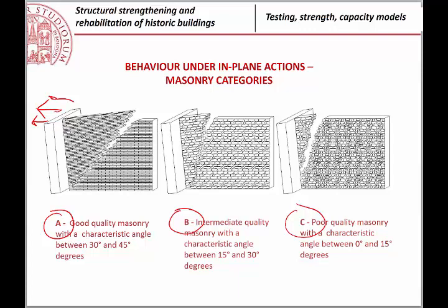talking about what Professor Borardi said, this is what we call a local mechanism, okay, you remember, but we will go into details for it. But it is very important that if they are connected and you have a good quality of the masonry, you see that the crack that will be formed is inclined, and this angle of inclination is quite large.